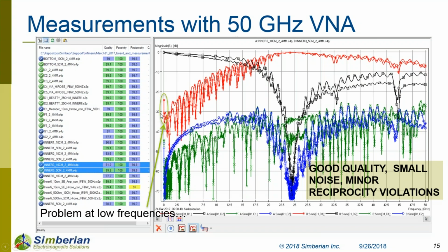All three vendors told us that when it comes to calibration of vector network analyzers, the most accurate method for calibration is using electronic calibration. In the case of the Keysight PNA, the electronic calibration kit has built-in DC blocking caps. And this is used in case we are measuring active devices. So if you have some DC bias across the cables, you can actually damage the calibration kit. So they put DC block caps, but this compromises the accuracy of the source matching in the 10 to 50 megahertz region. So your reflection coefficient is really inaccurate in this low region, and this makes extrapolation down to DC something you cannot trust. And we need this in order to get a DC point.